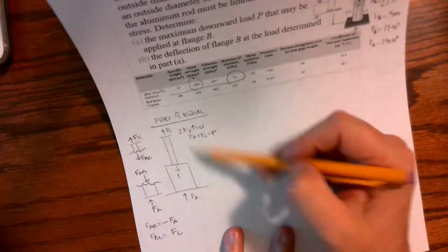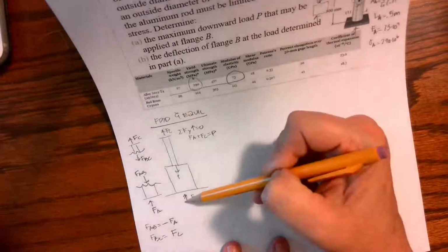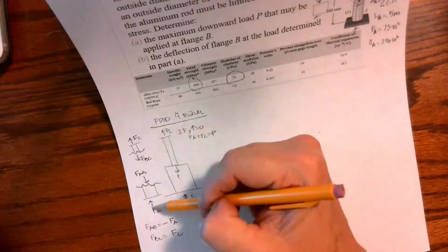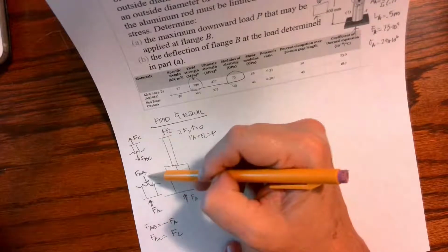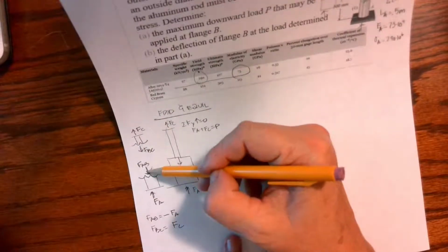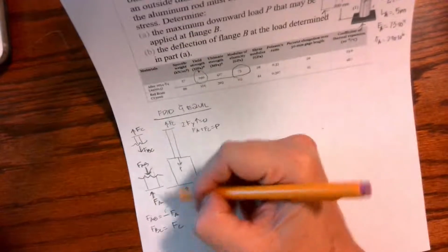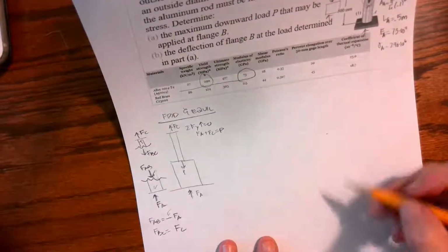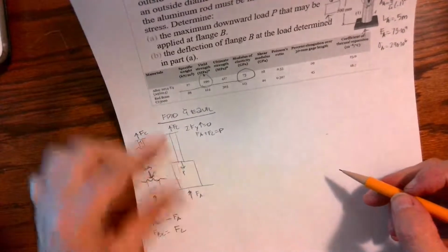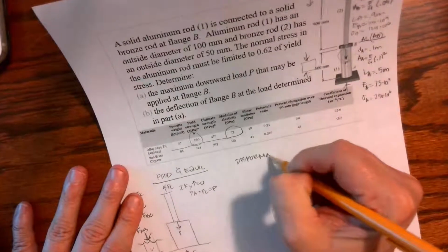So I have this set up with equilibrium. I'm going to assume both of these are pulling up. If this is pulling down, we have to be pulling and pushing. So internal, I would assume in tension, but based on equilibrium, I would find it is in compression. So my internal FAB is negative FA. That negative tells us that it's going to be in compression. FBC equals FC. Positive tells us it's in tension. That makes sense with my picture. Pushing, pulling. Okay? So now, step 2, deformation. And we start with our geometry.